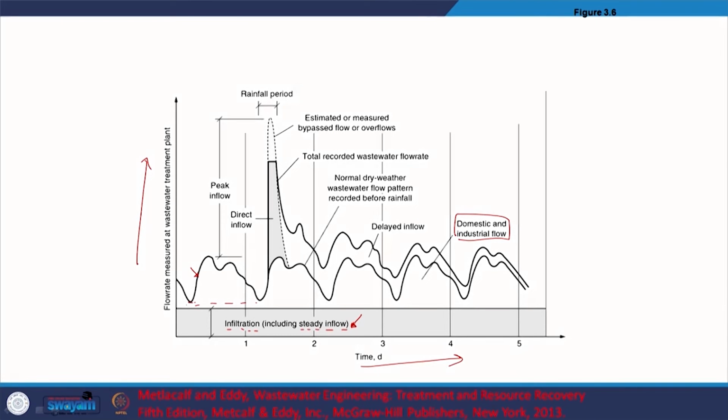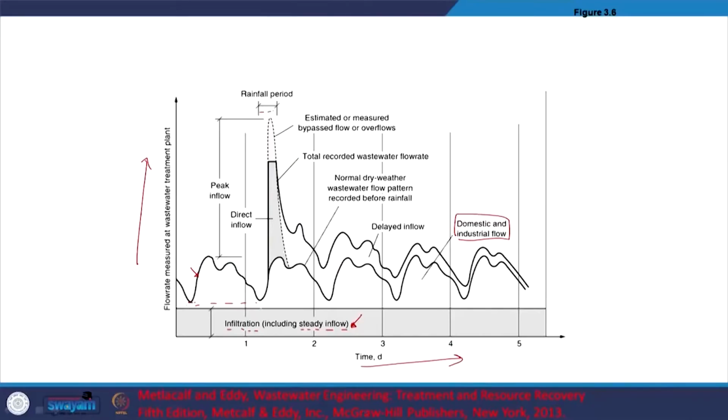And then what do we have? Let's say we have a rainfall period out here. Obviously, mostly in India, you have open sewers. Only now are we going for underground sewers and such. In India, we have combined sewer networks, let's say, both for the stormwater and for your domestic sewage. So a lot of the runoff from rainfall events typically ends up in your wastewater treatment plants.